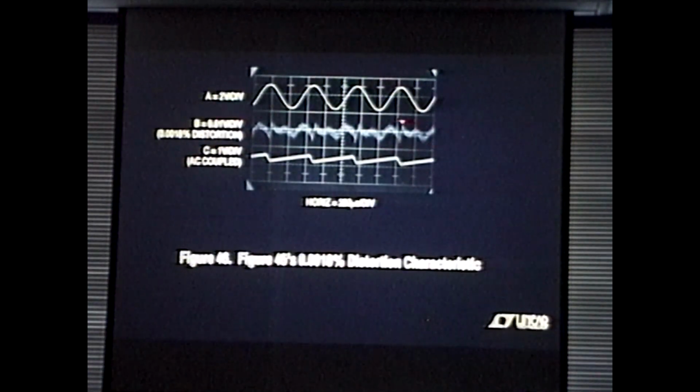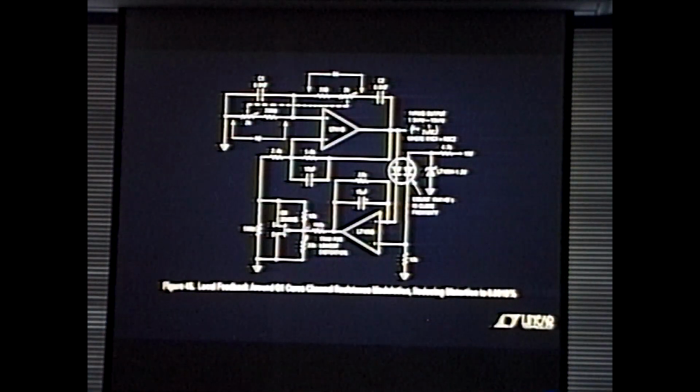Now you look at that, you feel pretty good, and you say, what would be nice would be to get rid of this trim. In fact, what would be nice would be to come up with a gain control mechanism that inherently doesn't have this problem. It's always nice to be able to trim away a circuit problem. Tweaks are neat. Everybody likes them. It's always nice to turn the knob and see the problem go away. But architecture wins over trimming every time. What you want is a scheme down here that inherently doesn't care about channel modulation effects. That's the ultimate trim, is the architecture requires none.